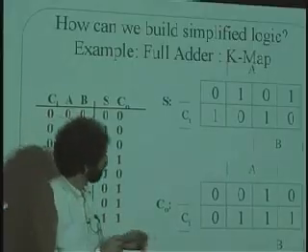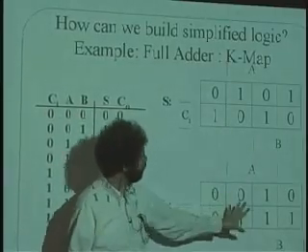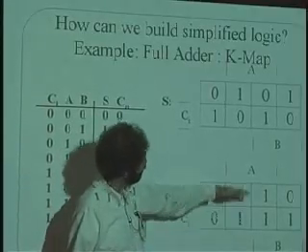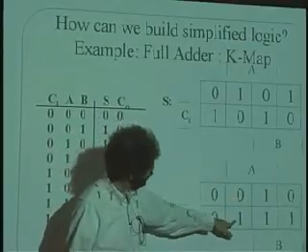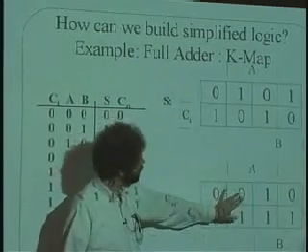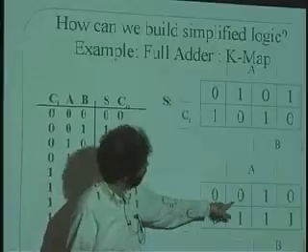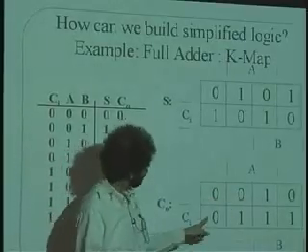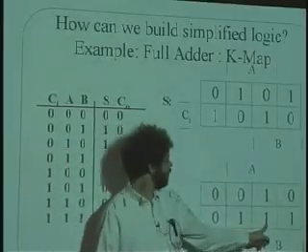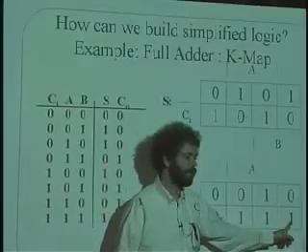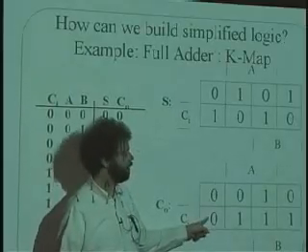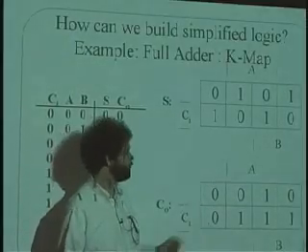So whenever I move across a border to a neighboring cell right next door, only 1 bit will change. Furthermore, this isn't really a square grid. It's actually a toroid, in that this edge here is the same as this edge here. So if I'm going over here and I fall off the bottom, what I really mean is that I come back around and come to the top here. Now that doesn't matter so much when there's only 2, because going around this way is the same as going back and forth here. But let's say that I'm over here. I move like this, 1 bit will change. A changes from 0 to 1. Here, B changes from 0 to 1. Here, A changes from 1 to 0. And then I go 1 more, come back around to this side, and B has changed from 1 to 0.